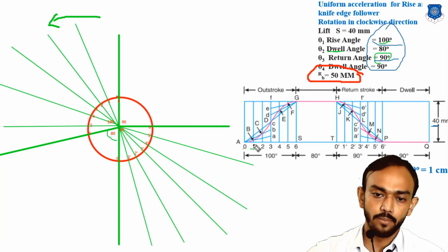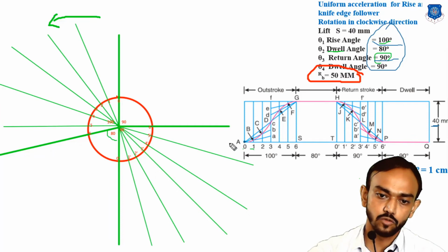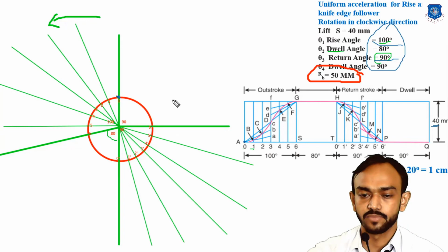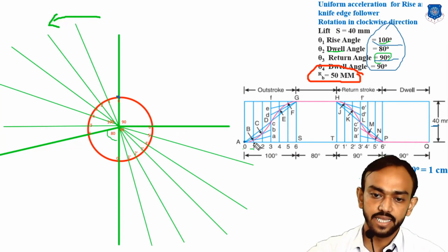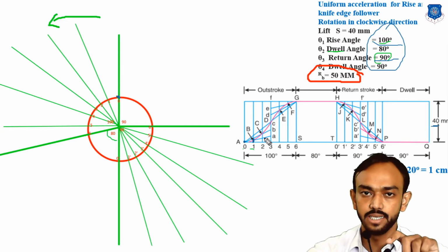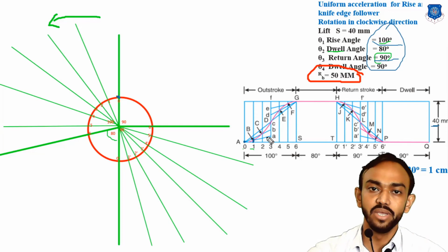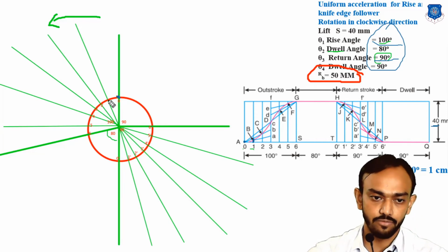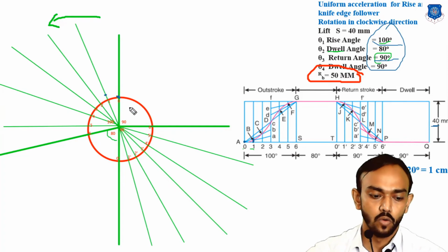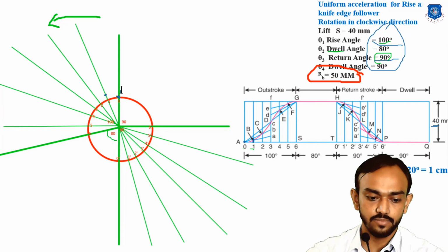We use the compass here, and we know that 0 and A are on the same point, so our A point will be here. After that, check here, the distance is given between 1 and B. We take the center at 1 and take the distance to the B, and we apply this distance from 1, and here we will get some point B.